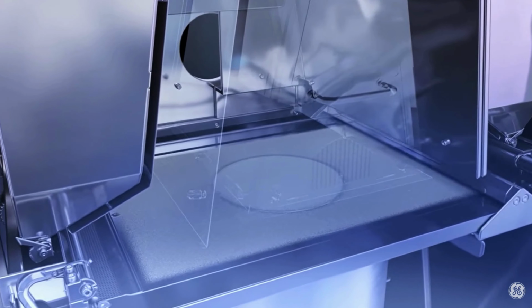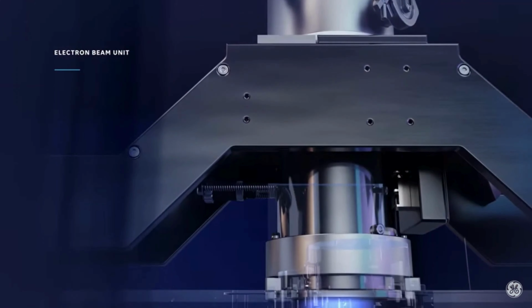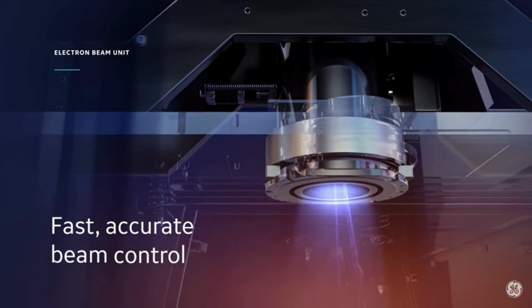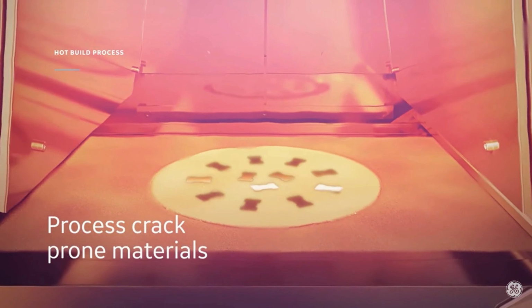In electron beam melting, metal powder is selectively melted layer by layer using an electron beam to create complex 3D objects. An electron beam generated from a highly focused electron gun is directed onto the metal powder bed. This beam moves according to the programmed path, selectively melting the powder in specific areas corresponding to the cross-section of the part being manufactured. Electron beam melting is performed in a low-pressure vacuum environment, with a small amount of inert gases used to remove gaseous byproducts and oxygen.